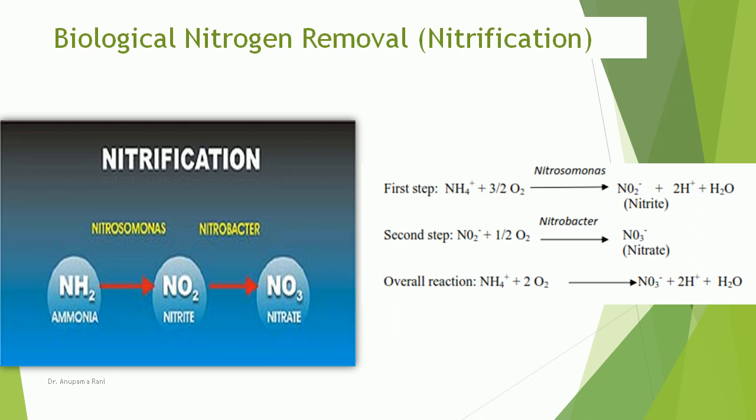Now coming to the concept of biological nitrification and denitrification. Bacteria remove ammonia nitrogen from wastewater by a two-step biological process, nitrification followed by denitrification, to convert it finally to gaseous nitrogen. In this gaseous form N2 is inert and does not react with the wastewater itself or with other constituents present in wastewater. Since treated wastewater is likely to be saturated with molecular nitrogen, the produced N2 is simply released to the atmosphere. These two steps require different environmental conditions and hence generally they are carried out in separate reactors.